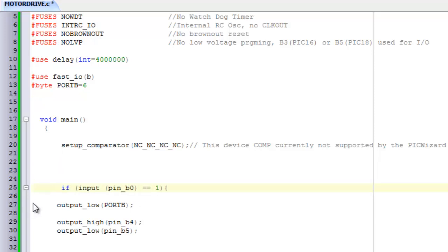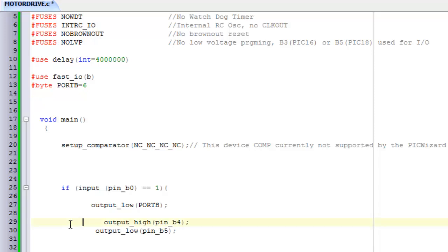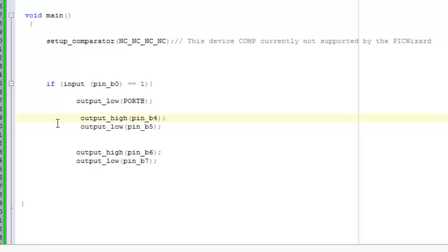And here I have a very important function that you will basically need all the time, because what we're doing in this part of our course is that for an input, we are going to have an output. So we always have to use this function called a conditional function. The conditional function is going to ask the MCU for the state of a pin. What is the state of a pin? Either 0 or 1, depending on whether it's on or off.